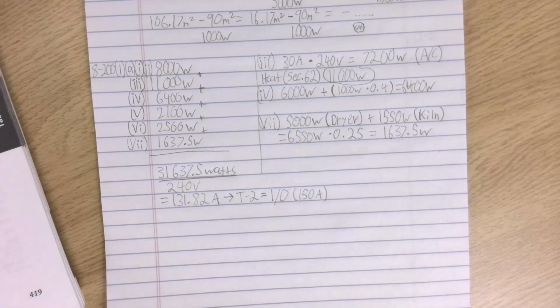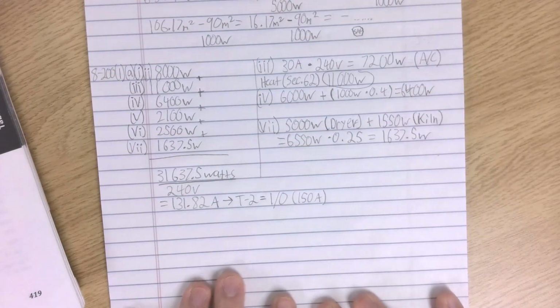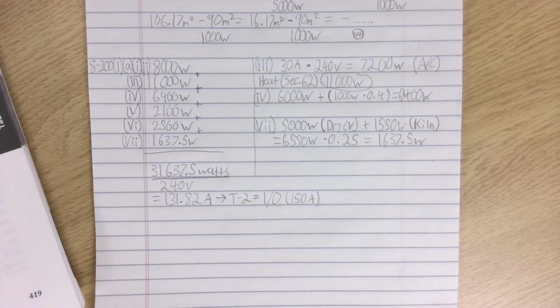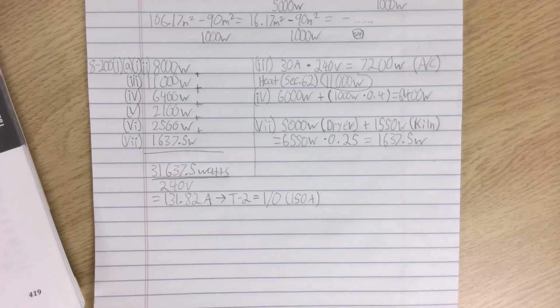And when we size overcurrents in general, and I'm saying general because we're working off a general section of the codebook. If you remember that, if you don't, you can go look back at the preface to see what's general sections of the codebook and what are the supplementary or specific, or I say boss sections. But we're in a general section. So in general, we size our overcurrents to protect the wire. The wire is sized to deliver current to the load, but if that wire breaks, it's all for nothing. So we size our overcurrent to protect the wire. And in code class, we're going to do maximum overcurrent and a minimum wire size.